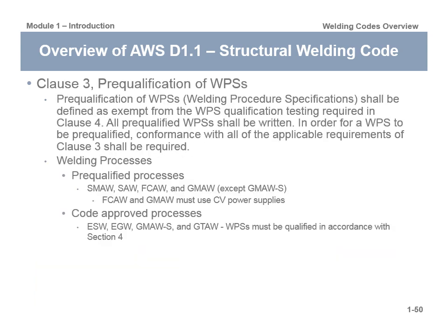Prequalification of WPSs, Clause 3. Prequalification of WPSs shall be defined as exempt from the WPS qualification testing required in Clause 4. All pre-qualified WPSs shall be written. In order for a WPS to be pre-qualified, conformance with all the applicable requirements of Clause 3 shall be required.